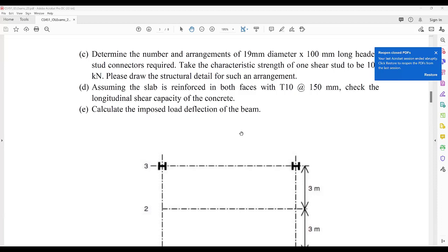Now check the adequacy of the whole composite beam in the serviceability limit state. I solved it with you. It was very simple. We add a variable to the composite action on prop construction. Is it propped or unpropped? Execution stage and those things. Do you remember? Yes. You understood execution stage and composite stage. So all that will come. And we calculated I using the parallel axis theorem. Do you remember? Yes. It's the same thing.